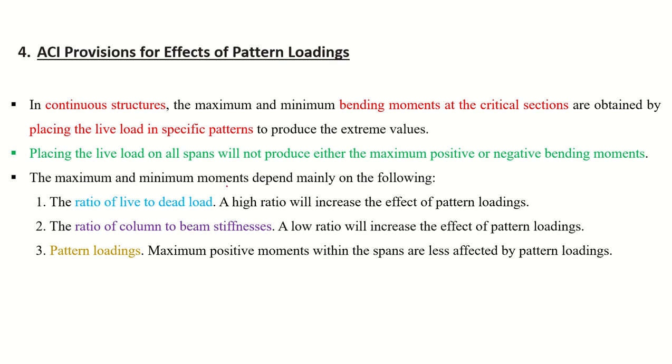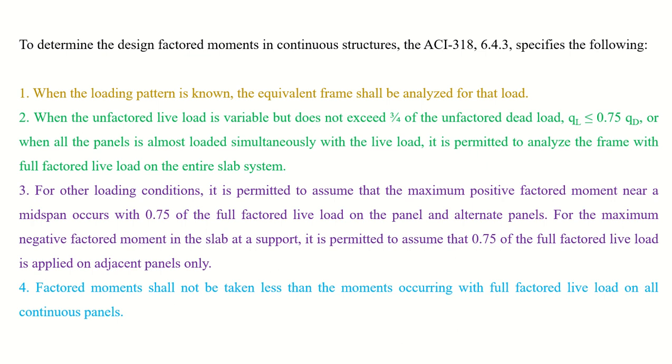So the maximum and minimum moments depend mainly on the following. Number 1, the ratio of live to dead load. A high ratio will increase the effect of pattern loadings. Number 2, the ratio of column to beam stiffness. A low ratio will increase the effect of pattern loadings. And third, pattern loadings. Maximum positive moments within the spans are less affected by pattern loadings. To determine the design factored moments in continuous structures,